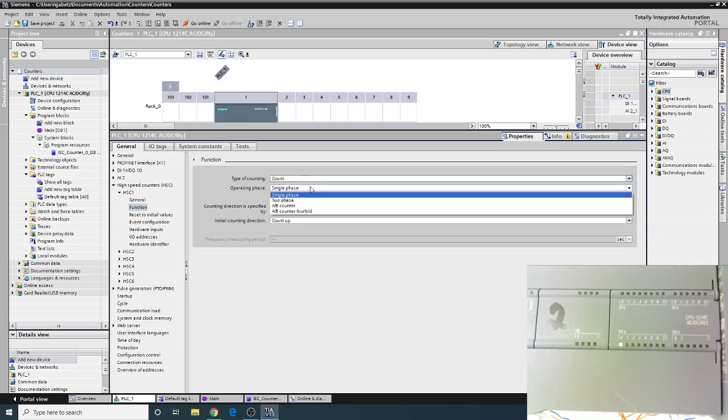And what these high-speed counters are truly meant for is encoders. Now, what is the point of an encoder? An encoder tells you the position of a motor, most often a motor. So CNC machines, ideally, you're going to have encoders on them. The computer is going to tell the CNC machine to move from point A to point B. Ideally, you have that encoder there, which actually counts how far it has actually moved.